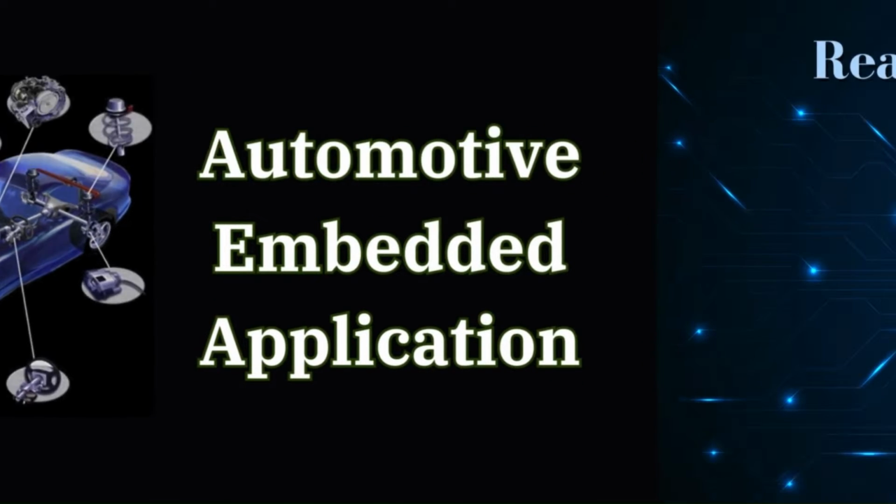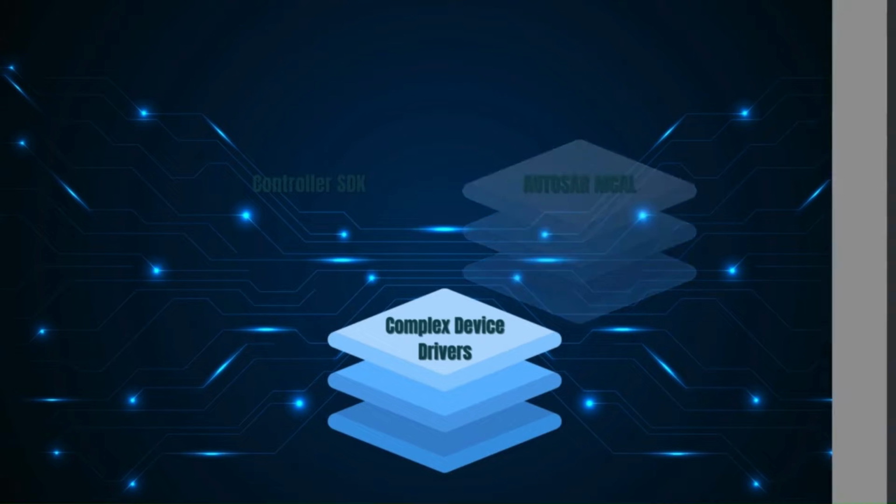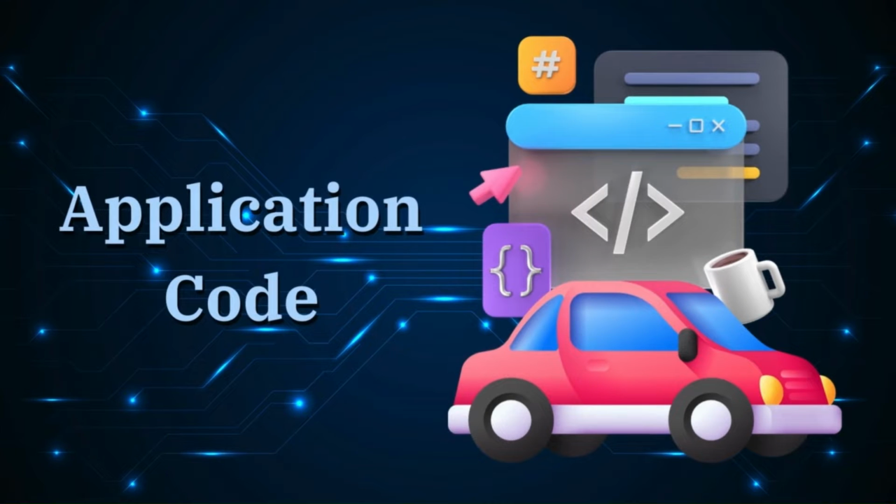Now, what AUTOSAR technology has done is, whatever automotive embedded application you want to develop, the RTD real-time driver files that you will need to develop that application would be the same irrespective of the microcontroller that you are using, whether that microcontroller is from NXP, Renesas, Infineon, etc.